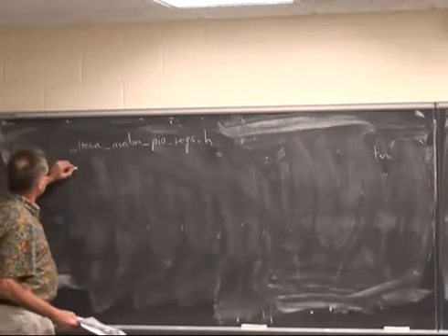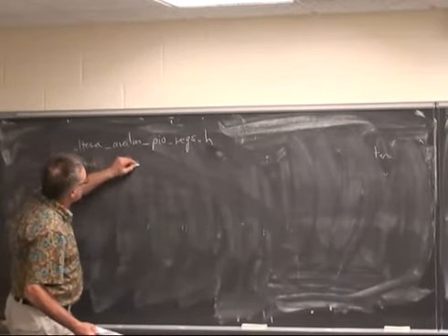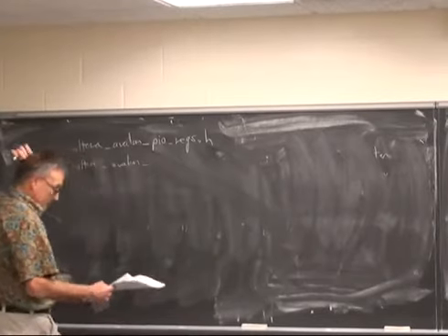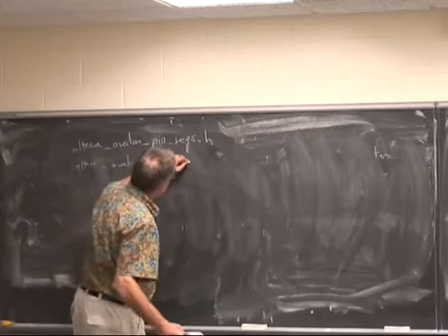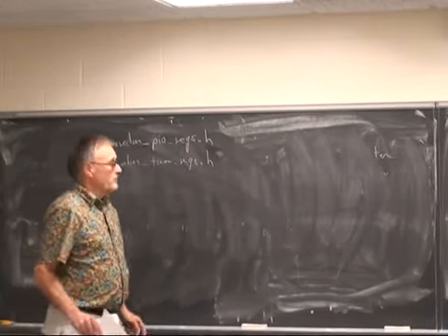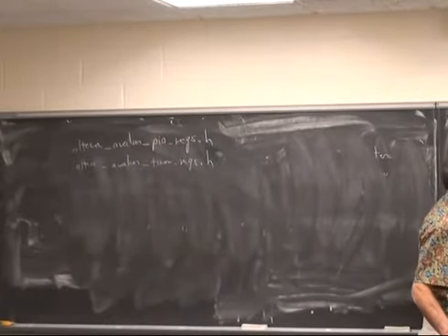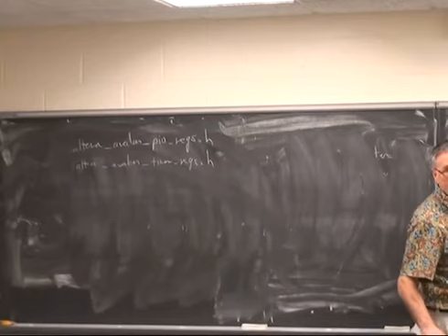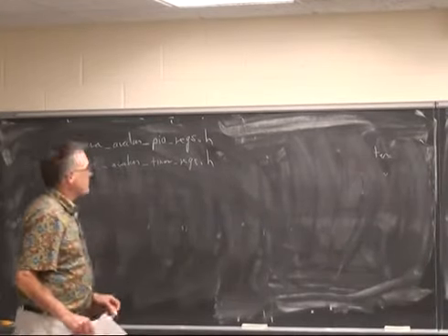Or if you look up Altera Avalon timer reg.h, you'll find a set of macros that packages up the I/O read and the I/O write at a slightly higher level, for perhaps more ease of use.